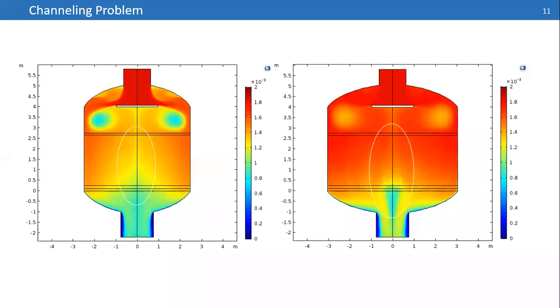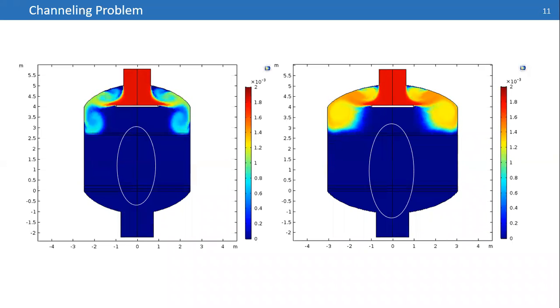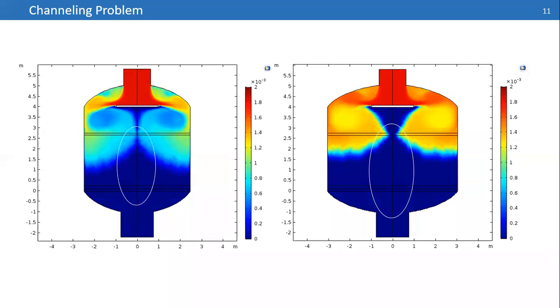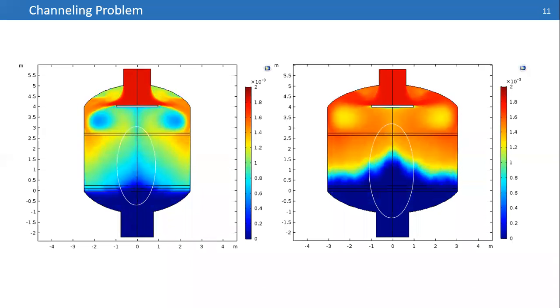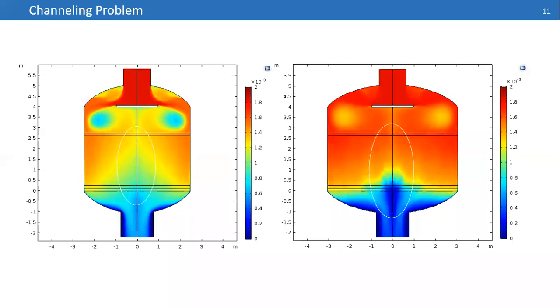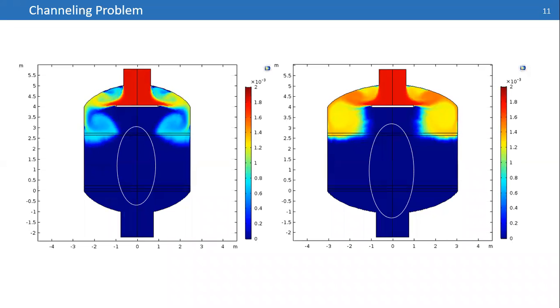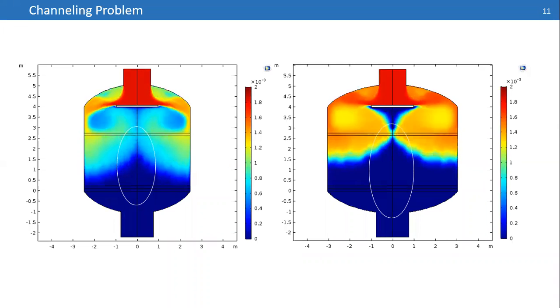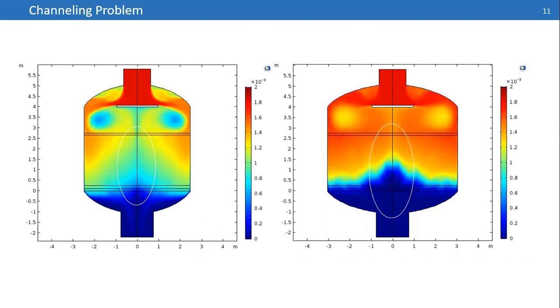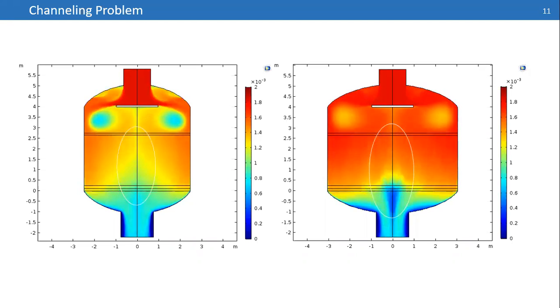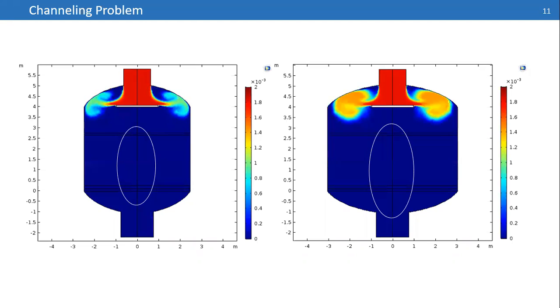Most of you know what RTD analysis is. RTD is the study of the residence time distribution inside of your reactor, and when you are doing RTD analysis, you are investigating the profile of the behavior and hydrodynamics of your bed, and seeing what is the residence time of different components inside of your catalyst.